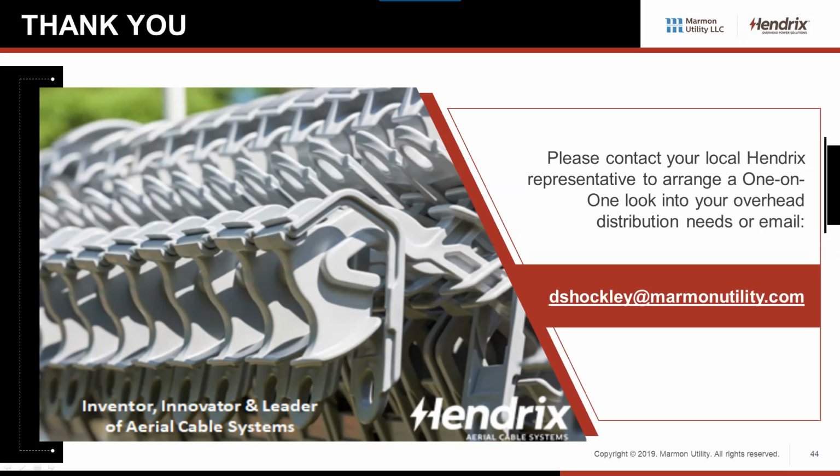Obviously, you're going to remove the covering for equipment taps for transformers, so there's already an arrester there to protect the equipment. Where we don't tend to see them as much as we'd like is for taps. But a lot of utilities are doing more: if there's a single-phase or three-phase lateral tap, they'll hang a cutout and a set of arresters there. So that's what we like.